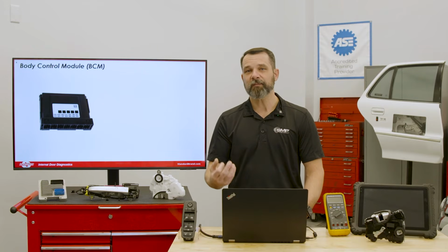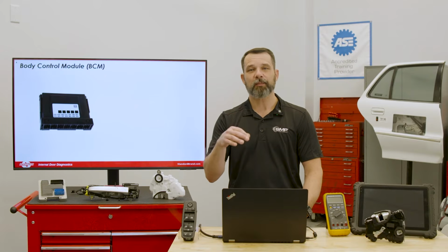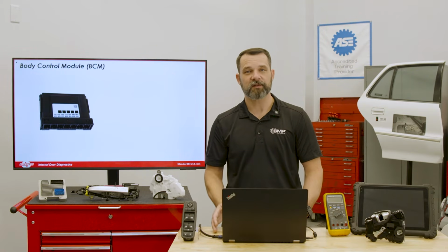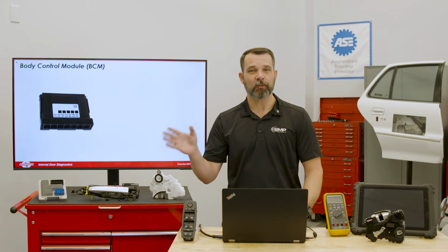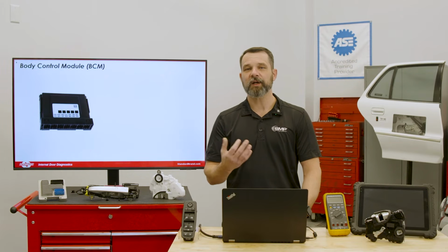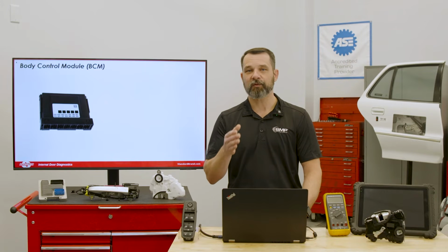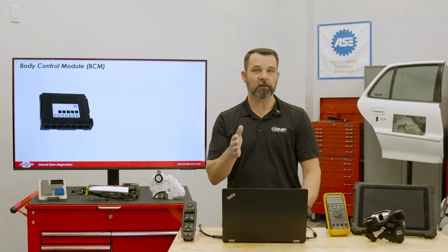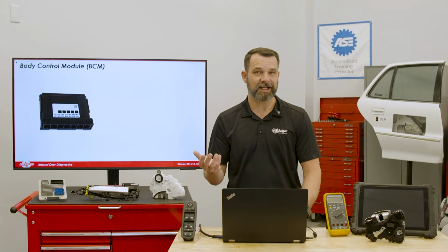Now it's going to receive inputs from things like the switches, fobs, and sensors, and it's going to output commands for things like the locks and the window motors that we just discussed. So they're often the brains behind smart door modules as well. Now, the body control module is going to act like the hub of the vehicle's body network, right? And instead of sending power directly to the actuator, it actually sends a digital command to smaller modules in the door, or it triggers relays depending on the design that it has.